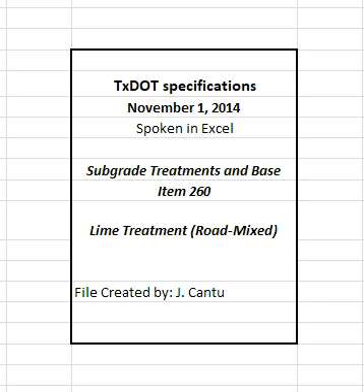4.6 Reworking a section. When a section is reworked within 72 hours after completion of compaction, rework the section to provide the required density. When a section is reworked more than 72 hours after completion of compaction, add additional lime at 25% of the percentage determined in Section 260.2.6, mix design.